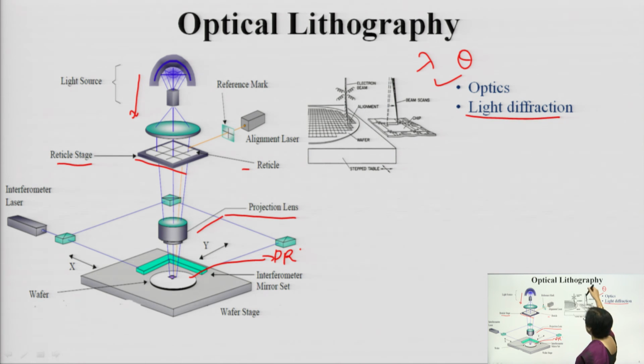when you are projecting or exposing, the light beam is getting projected, so you have some diffraction happening, as we have seen in the previous lecture, depending upon the different distances at which the mask is being placed. There is one more reason due to which diffraction happens: if there is unevenness in the PR coating also, you can have a diffraction pattern.